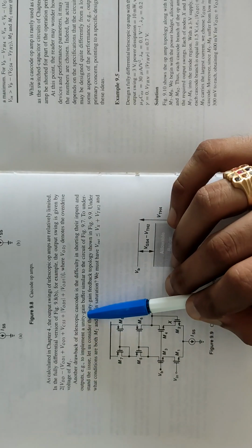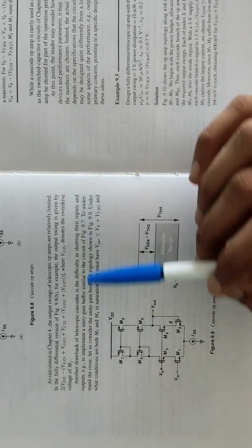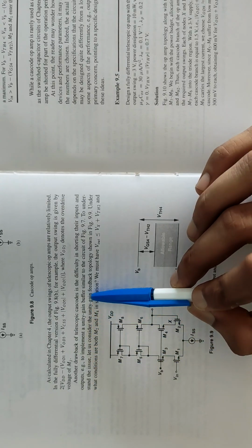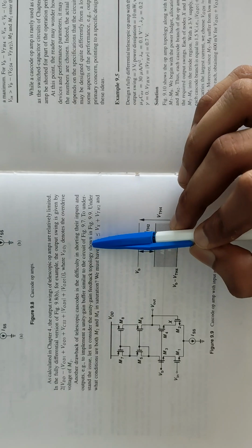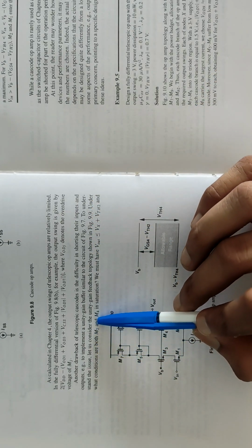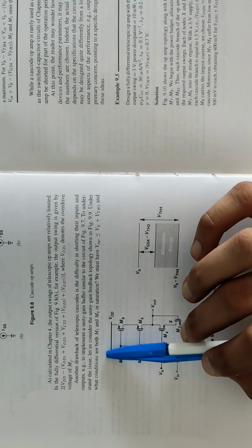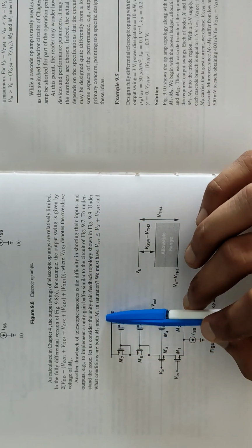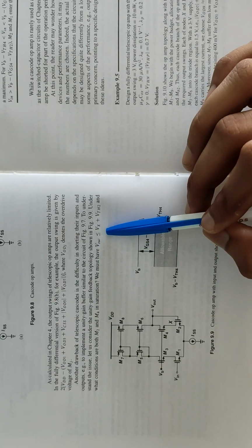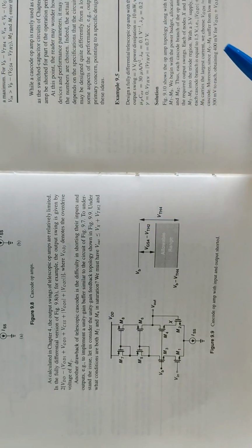Another drawback of telescopic cascodes is the difficulty in shorting their inputs and outputs, for example, to implement a unity-gain buffer similar to the circuit of the figure. To understand the issue, let us consider the unity-gain feedback topology shown in the figure. Under the condition of both M2 and M4 in saturation, we must have Vout less than or equal to Vx plus VTH2